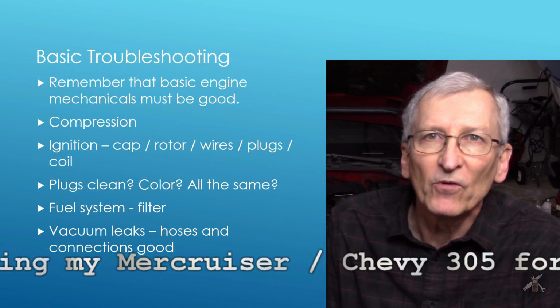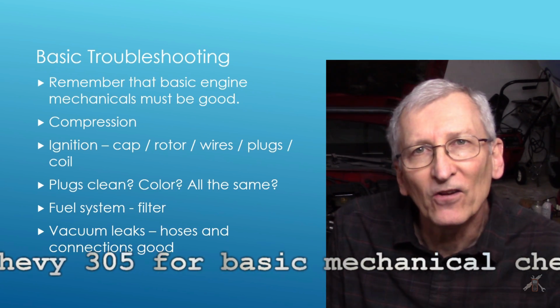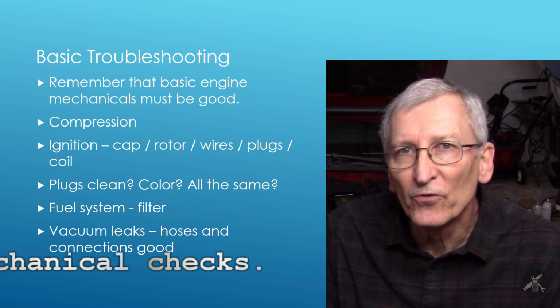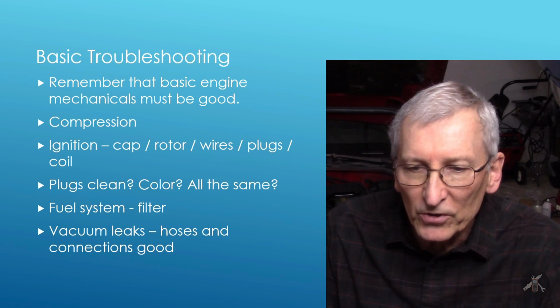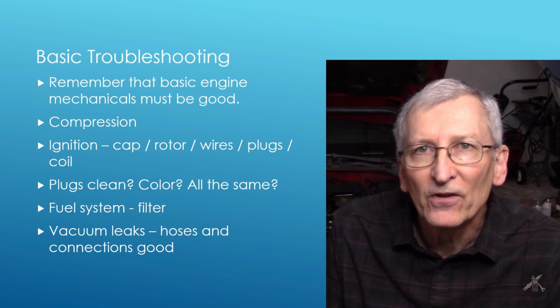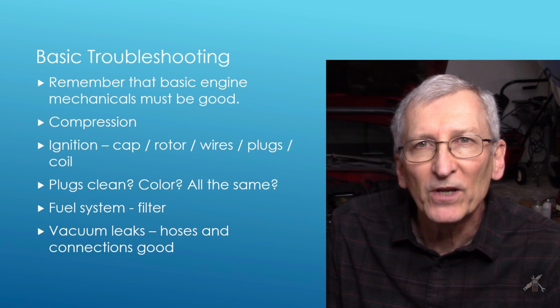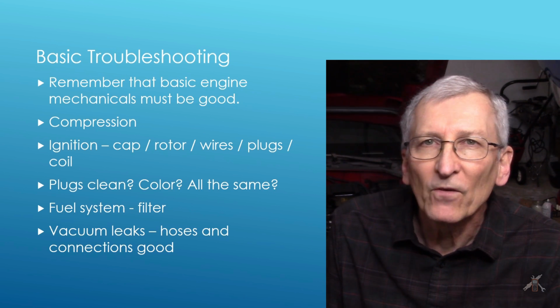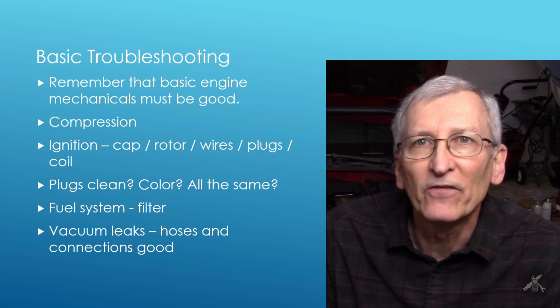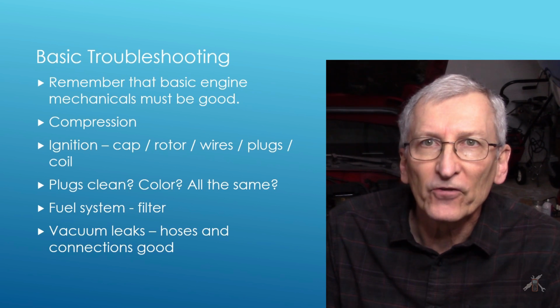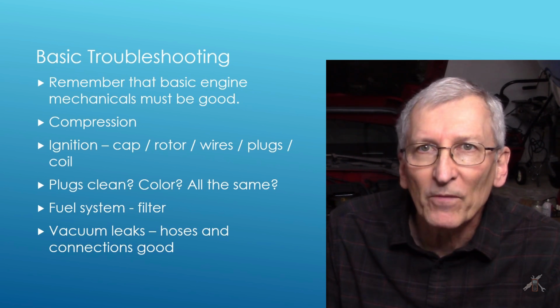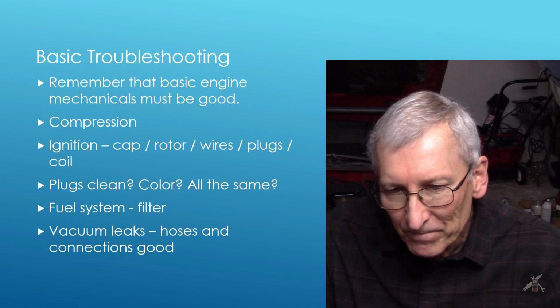Vacuum leaks. Again, before you get into diagnosing things, check all the vacuum hoses. Brake booster, purge charcoal canister. Make sure all the hoses are good, because a vacuum leak, sometimes even what looks like a small leak in a vacuum hose, will knock your system off, right? You want to make sure your hoses are in good shape.